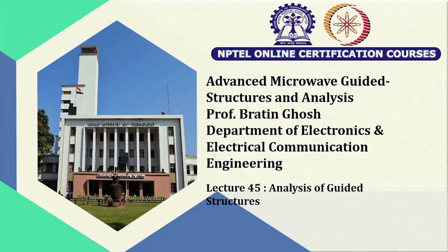So, welcome to this session of lecture on analysis of guided structures. We are going to start this session of lecture with the analysis of the partially filled rectangular waveguide. Now, we had already found out the propagation characteristics of rectangular waveguides filled with homogeneous material. We found that the TEz and TMz modes adequately describe the mode spectrum inside rectangular waveguides filled with a homogeneous medium.